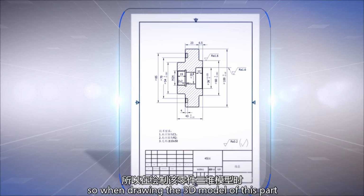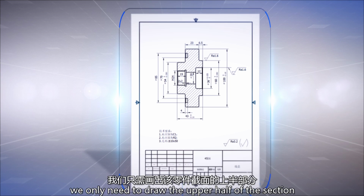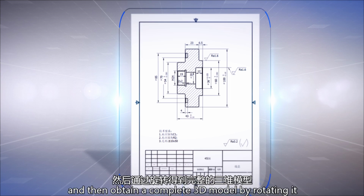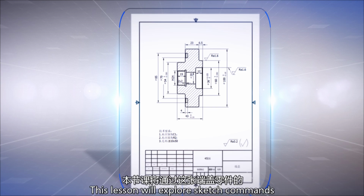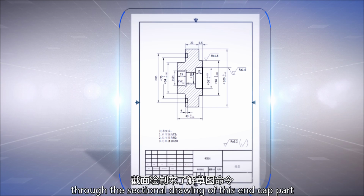So, when drawing the 3D model of this part, we only need to draw the upper half of the section, and then obtain a complete 3D model by rotating it. This lesson will explore sketch commands through the sectional drawing of this end cap part.